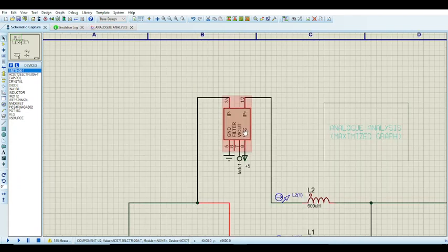The advantage of the shunt is that the readings are much more stable than Hall effect. Hall effect sensors are great, but sometimes they sort of struggle in these kinds of situations. Obviously, you could go with high-end current sensors. They're also Hall effect, but more stable. You could use them, but they're more expensive. I knew of one, but I forgot the name of it.